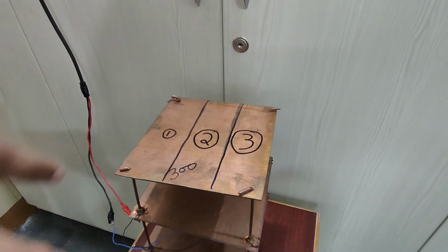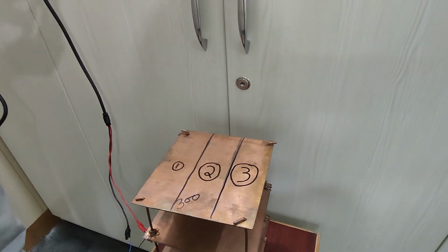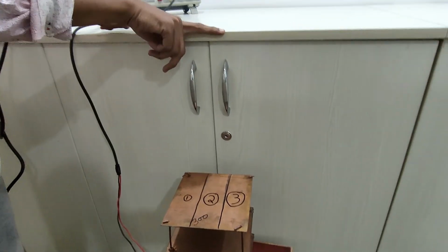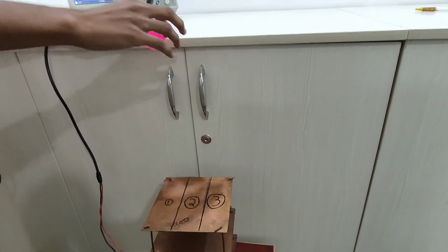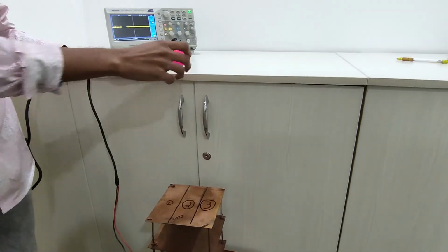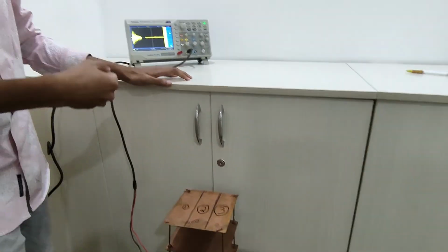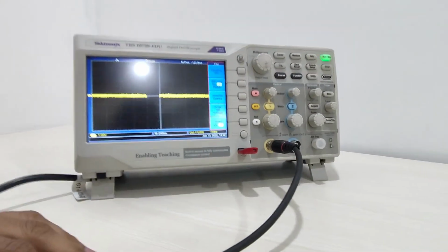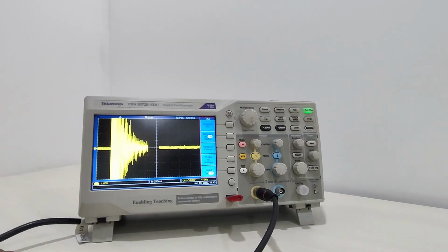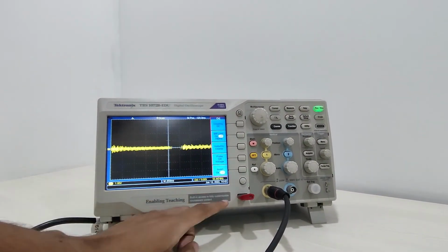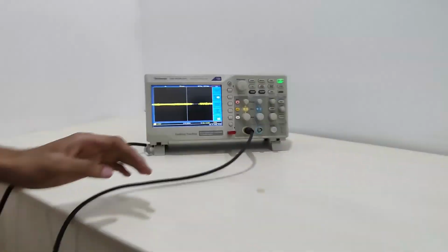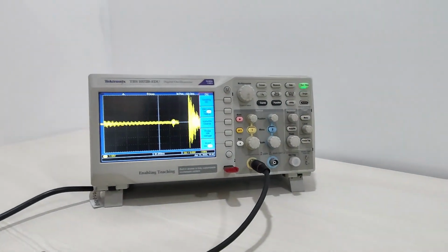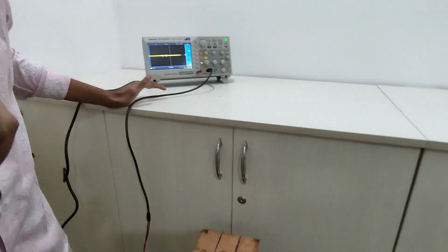For this excitation collection, we are going to use the drop hammer, as we discussed. The drop hammer length we have decided is 27 centimeters, which comes until over here. From here we are going to drop this ball weighing 44 grams. Then we collect the data response, and feed the response to this pen drive. Once we collect the data from all 3 responses, we go into analytical modeling in MATLAB.